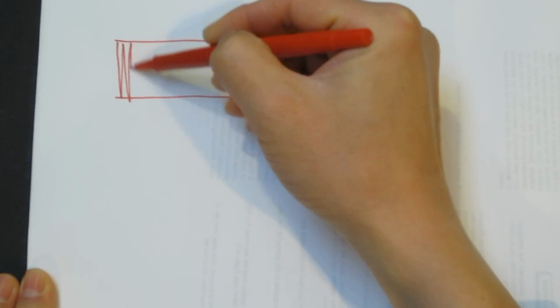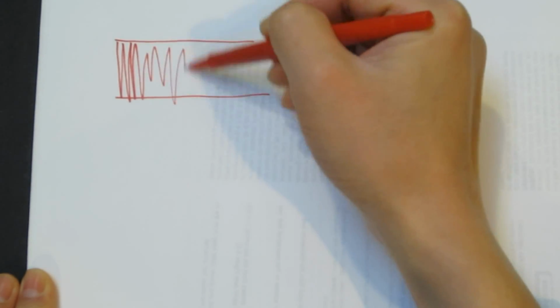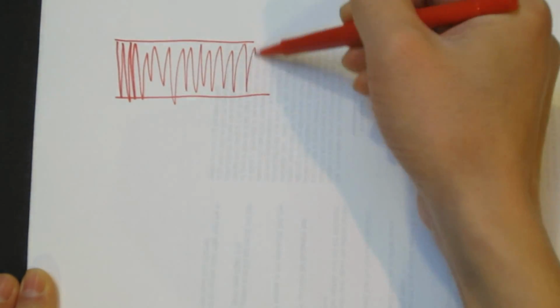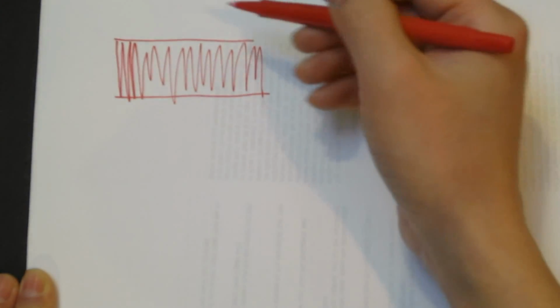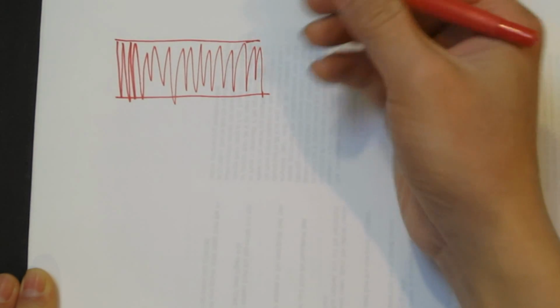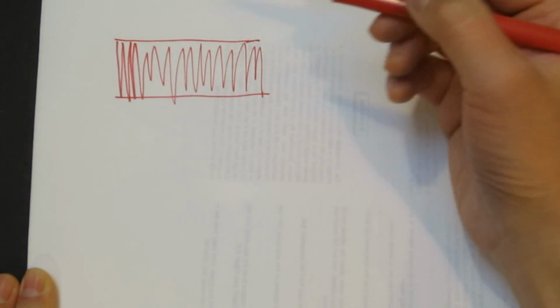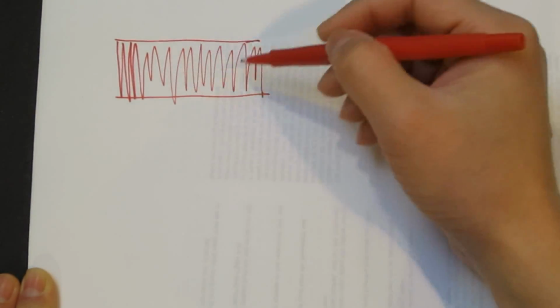There's not too much to it. So how about FM signals? As it turns out, FM is a little bit harder because FM signals have a constant amplitude, or the amplitude doesn't really matter. It's the frequency variation inside the carrier signal that encapsulates the information being transferred. So let's take a look at this FM signal.